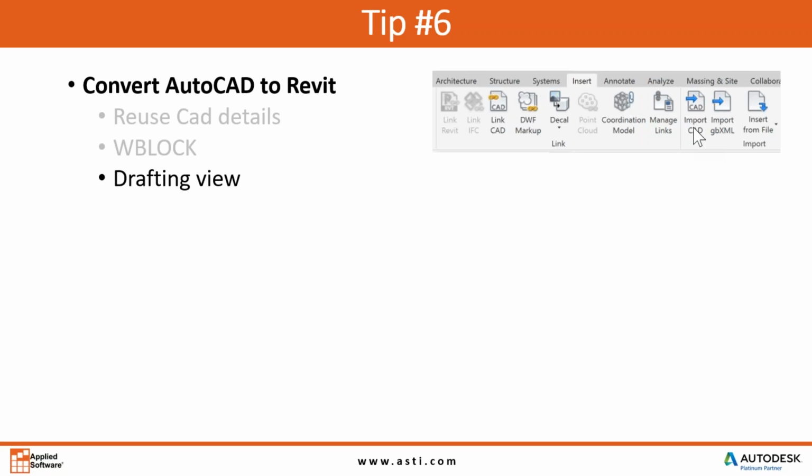My biggest thing, and my tip, if you will, the 6.2, 6.3 tip, is I like to potentially link a CAD detail in. That way, if I have somebody on my team who doesn't maybe know Revit, or is maybe still efficient or quick in AutoCAD, they can go back out to AutoCAD, adjust that detail in CAD, save it, and then it'll update here in Revit. It's totally cool. But you might want to import it if you're really just like, I'm severing the tie.